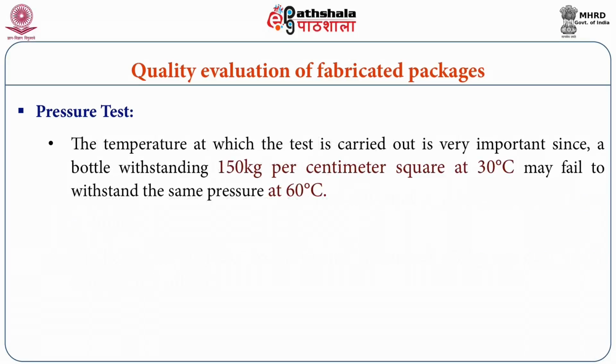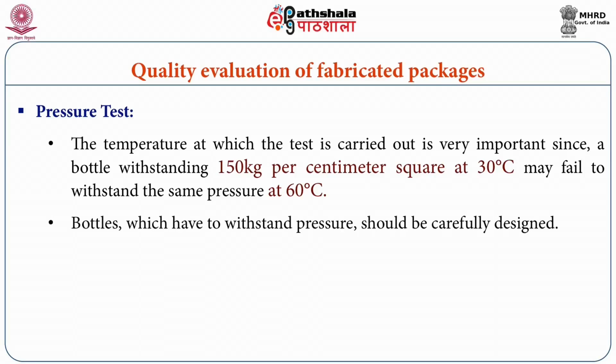The temperature at which the test is carried out is very important, since a bottle that withstands 150 kg per centimeter square at 30 degrees centigrade may fail to withstand the same pressure at 60 degrees centigrade. Bottles which have to withstand pressure should be carefully designed.